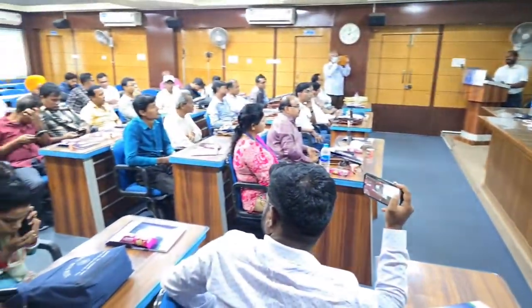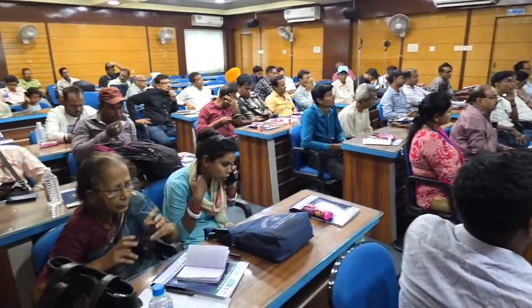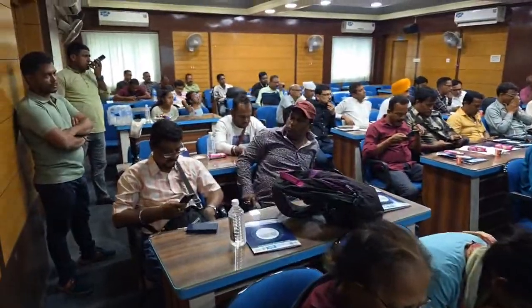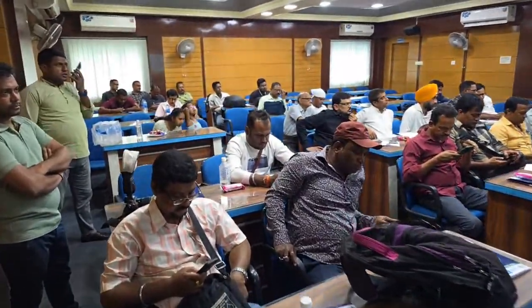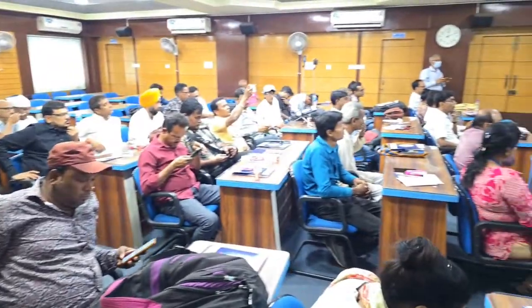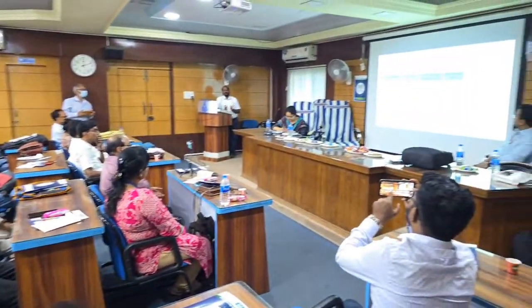From that case you can see the academic campus, the IIT ISM campus, is having a very low silt loading rate within our campus, because our entire campus does not have unpaved shoulders. You see that it is completely end-to-end paved. So the amount of silt loading is very less. But the public roads typically have high values, around 70 grams of silt per square meter of area.